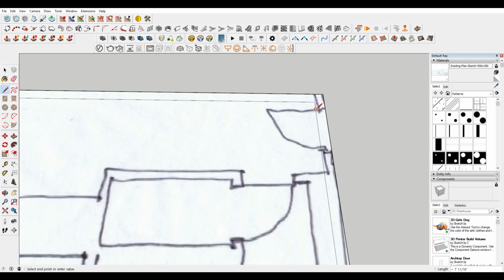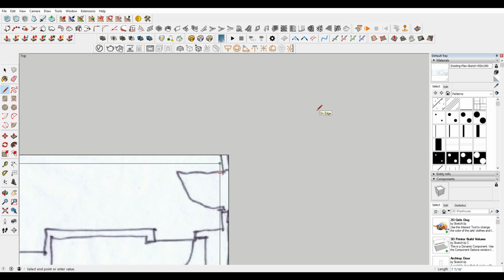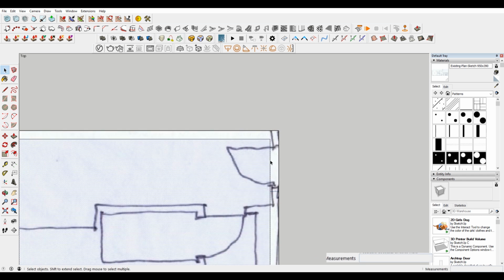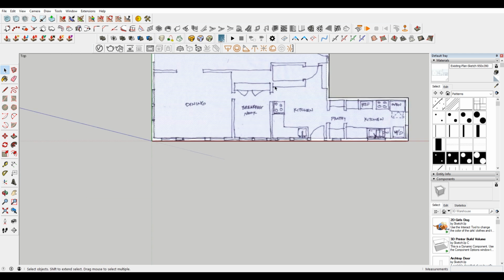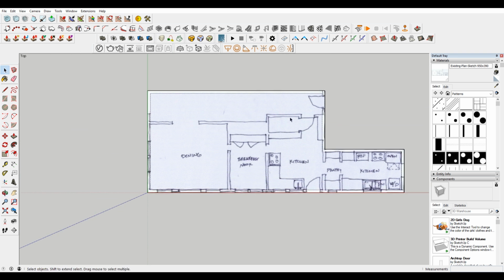We're just going to come in here, draw this down. So we have 7 inches about. So I'm just going to hit 7. I'm just going to make a little dot here you can't really see. And then assume that this is also 36 inches. So I'm just going to offset that 36. And then I can delete this little line there. I have this interior that I don't necessarily need.